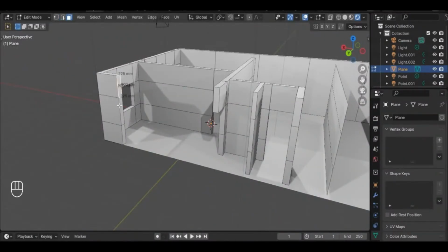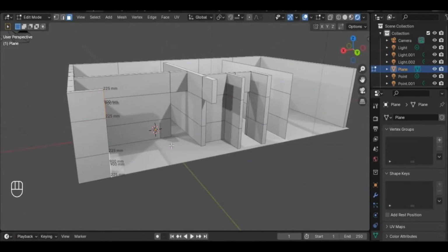So what I want to create a window, what I'll just do is I'll leave this middle and I'll take this, duplicate it, Shift D Y. Let's duplicate. So I'm creating 900 window, Shift D X. Let's go. But let me create 900 window, or let's create 750 window.